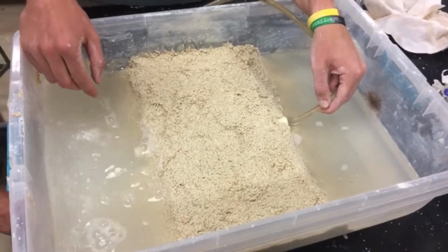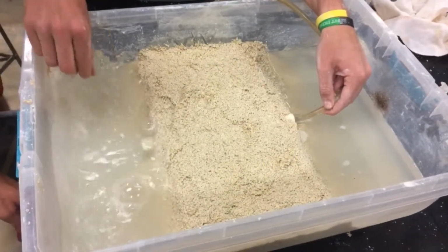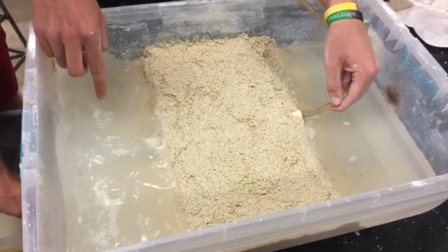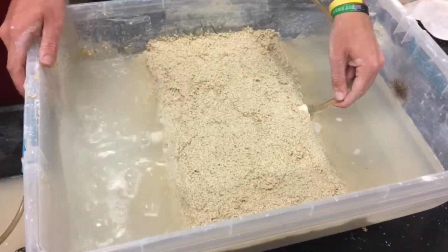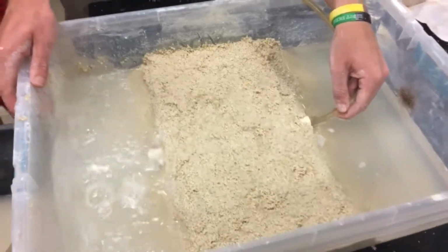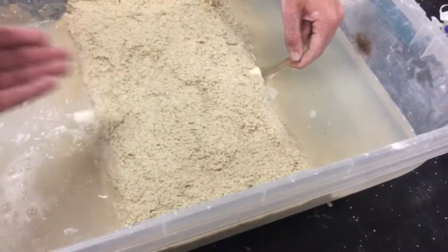This demonstration shows high velocity flow coming through the culvert, which causes erosion at the downstream end. Granular soils such as sand or gravel are much easier to erode than a clayey soil. However, they are necessary for the structural integrity of the embankment system and the support of the culvert pipe itself.